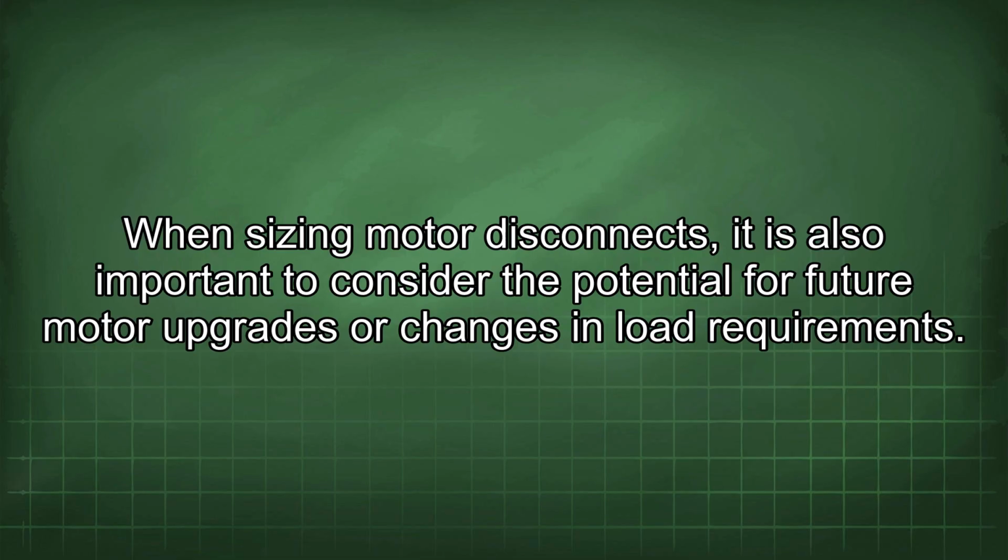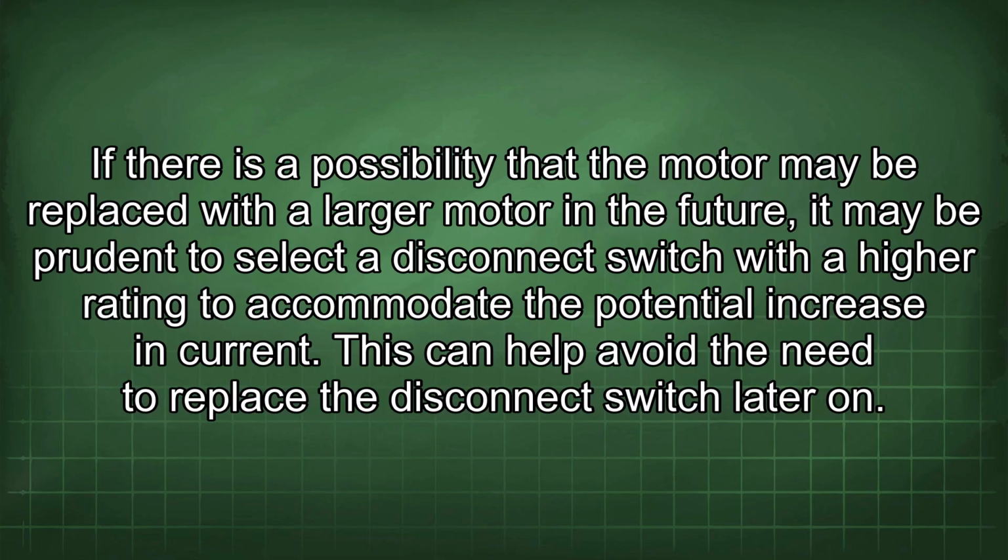When sizing motor disconnects, it is also important to consider the potential for future motor upgrades or changes in load requirements. If there is a possibility that the motor may be replaced with a larger motor in the future, it may be prudent to select a disconnect switch with a higher rating to accommodate the potential increase in current.